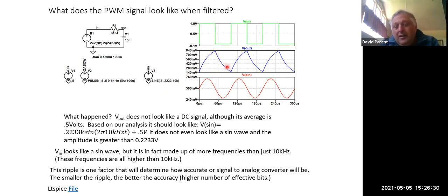And that's because, even though there's a fundamental frequency of one sine wave here, there's an infinite amount of sine waves that we have to sum up. This is the first one, but then we need the third, fifth, seventh, ninth. And I think in the lab manual, I took it out to 50 terms before Scopy couldn't really measure the difference.